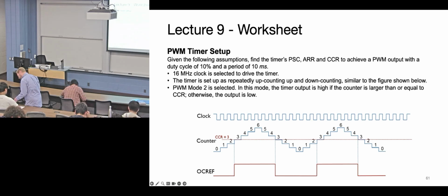Input is your clock. No, like this is your frequency. It's going to be prescaler plus 1. Plus 1, I need my clock to be right now a second, I read kilohertz. So you need less than 16 megahertz at 1 kilohertz speed. Okay, to slow it down. Yeah, you can slow it down by some division. It doesn't have to be a power of two.